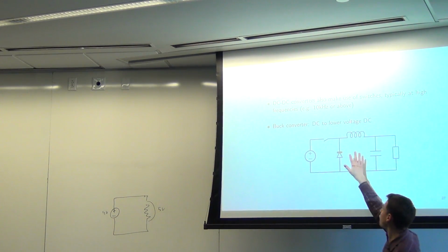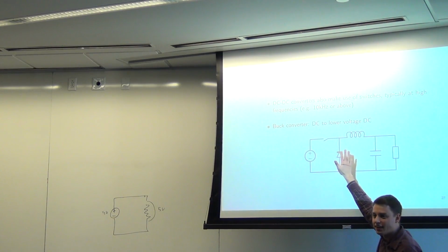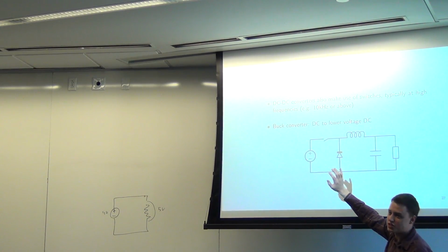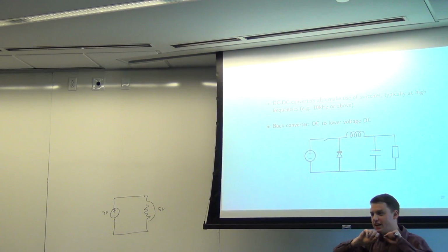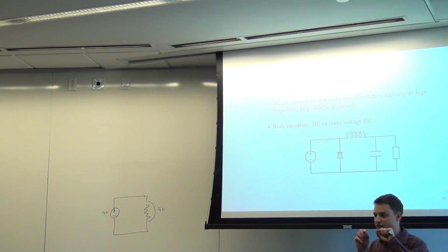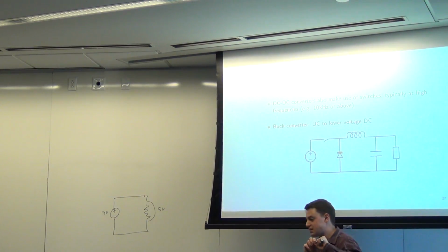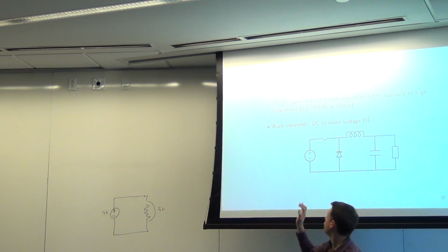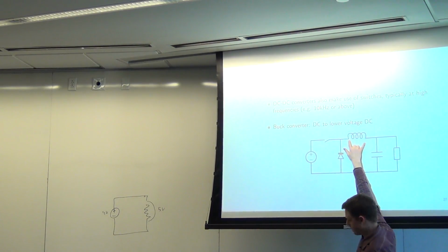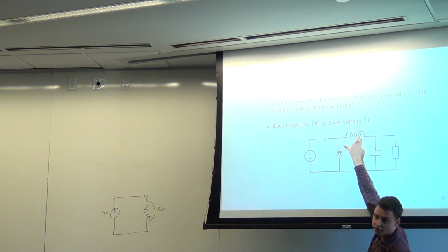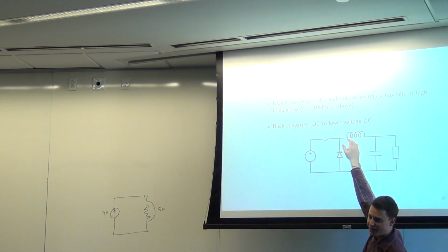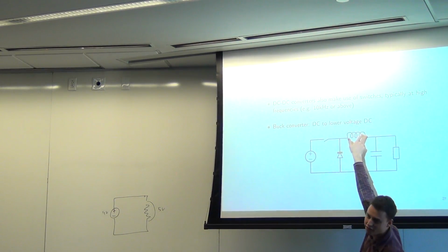Now, in order for the current to actually do that, this has to do interesting things with voltage. When the current's flowing through, there's a little bit of a voltage drop there, because it's not acting as an open circuit, so there is going to be a voltage drop across this. When it's the other way and this thing is open, the voltage drop actually reverses itself, and you actually get higher voltage here than there.